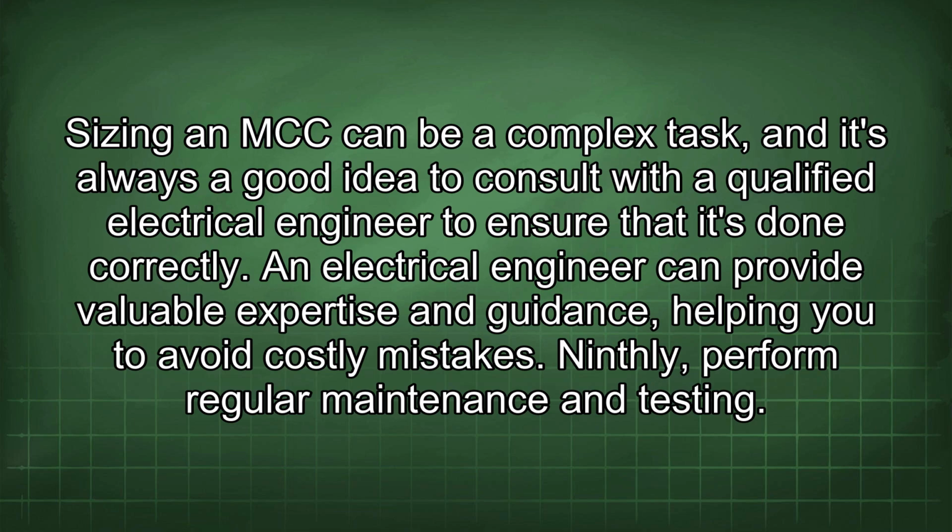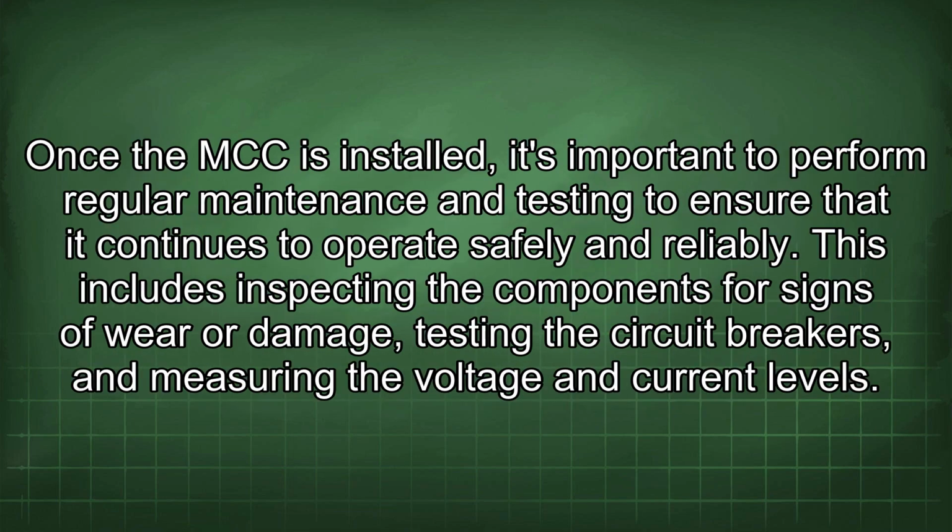Ninthly, perform regular maintenance and testing. Once the MCC is installed, it's important to perform regular maintenance and testing to ensure that it continues to operate safely and reliably. This includes inspecting the components for signs of wear or damage, testing the circuit breakers, and measuring the voltage and current levels.